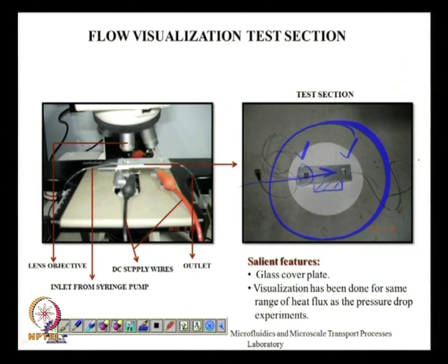And at the same time, you put a microscope over here and focus really down inside the microchannel to see the formation of the bubble. So, your physical observation of the formation of bubbles, the number density of the bubbles, the growth of the bubbles, how that process is linked to a change in pressure drop, a change in the friction factor, and whether or not you can say something about the heat transfer coefficient associated with such a process. So, the concept is to use heat transfer to change the surface and thereby to change the pressure drop.